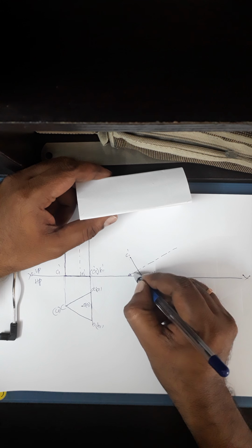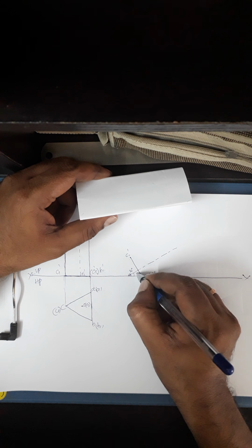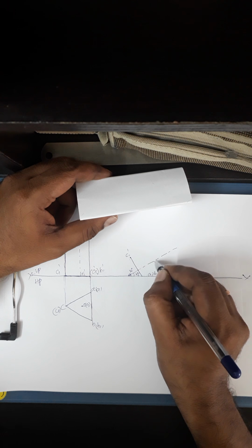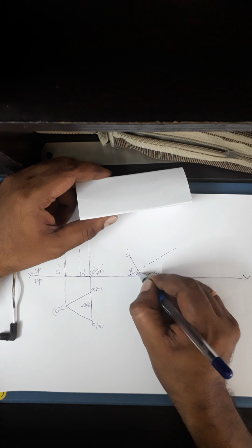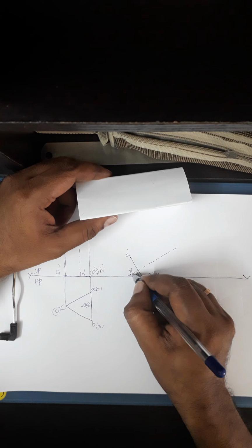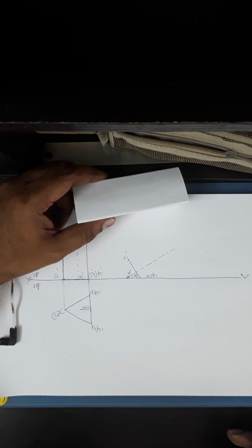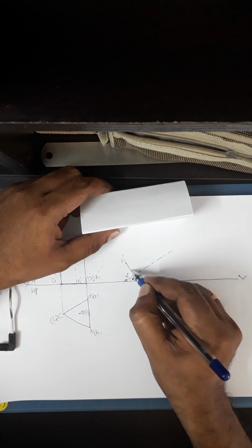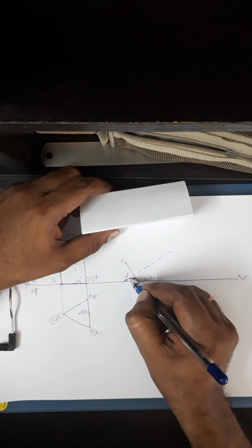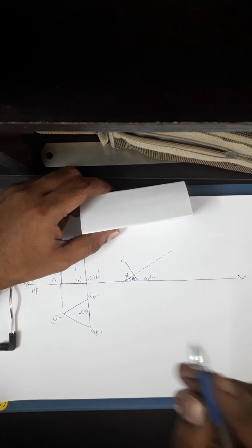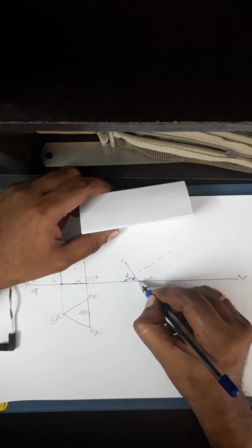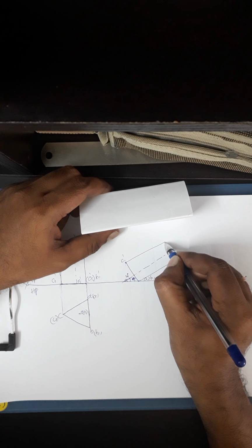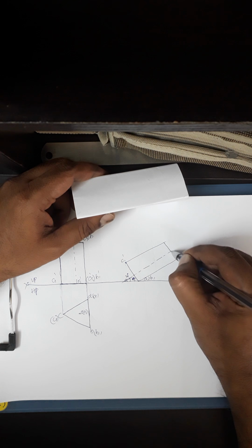If the axis inclines at 30 degrees, the base will be at 60. Because I've taken the base drawn at 60, and this axis line will be perpendicular to the base, this becomes 90 degrees, so these two should add up to 90 degrees. If this is 60, this has to be 30. In the problem it is mentioned that the axis is inclined, so don't dimension this; instead you take this at 60 degrees, but while dimensioning you dimension only this axis, saying the axis is inclined at 30 degrees to the horizontal plane. Then because all these longer edges will be parallel to the axis, or perpendicular to the base, you can complete the same view here.